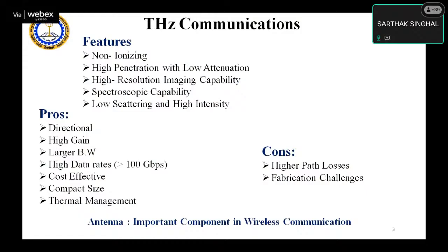The features of terahertz communications which make it a promising candidate are that it's non-ionizing. It has a higher penetration with low attenuation inside a wall and all components or whatever devices you are testing. It has a higher resolution for imaging capacities. Spectroscopic capabilities are there. It will provide low scattering and high intensity. All are due to its lower wavelength.